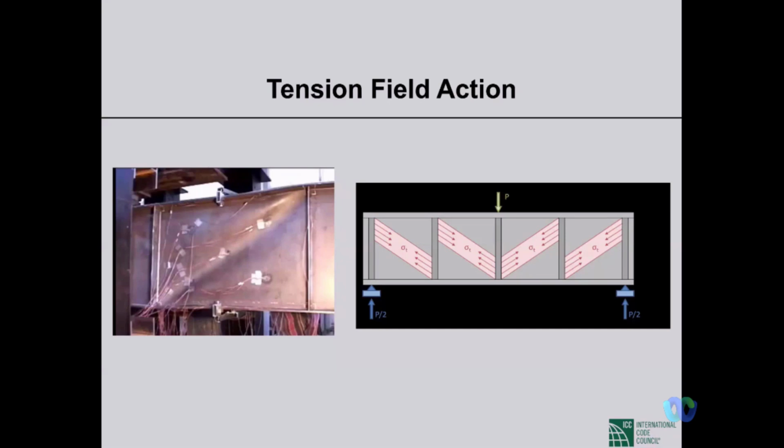So even after buckling, through the tension action that will act like a bracing, it will still continue to take load, because this part, as you can see, shown in the middle diagonally on the left side in a test sample, this is buckled, but in the middle you can clearly see something like a bracing. So that will still act like a bracing.